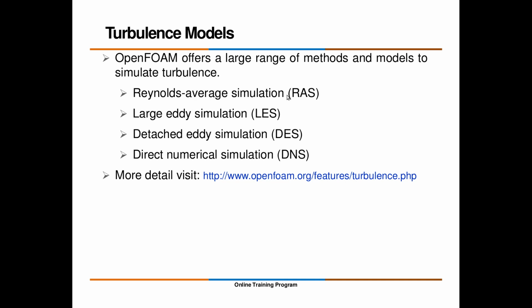And please believe me, whatever the most used turbulence models that people use till now, all are coded in OpenFOAM. But please don't straight away start using it and comparing the result. I say whatever you want to adopt from OpenFOAM, first make sure of your understanding. Maybe whatever they coded is correct, but for a different class of application, maybe you have to tune certain parameters. So before you use OpenFOAM for any of your projects, thesis, or any commercial purpose for your industry, I suggest first benchmark it, and try to verify whether the result is coming out correct or not.